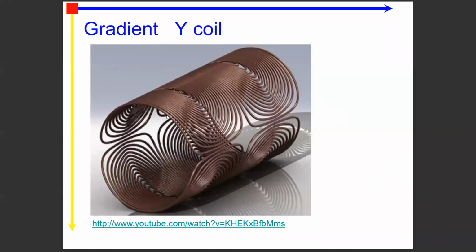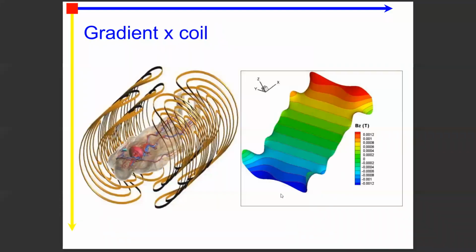So we discussed a little bit about gradient coils, the three sets in that example case. And you can see here how the winding patterns are very complicated. Normally, the way you optimize this structure is using some sort of stream function as the optimization function. You have a current distribution, which is a current density profile on the surface of a cylinder. Then you discretize this into current-carrying loops at the end, which creates a pattern. Then you construct this structure, and you have to then cool it. I'll show you later how it looks when it's manufactured. Often, for example, you might have, in this example case, secondary windings.